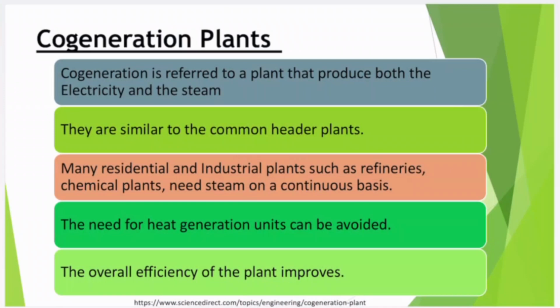So heat to electricity, electricity to heat will increase my loss, or the efficiency gets reduced significantly, because if the input-output of heat to electricity is 70% and electricity to heat is 80%, then the complete system is operating with close to 60%, even below that.